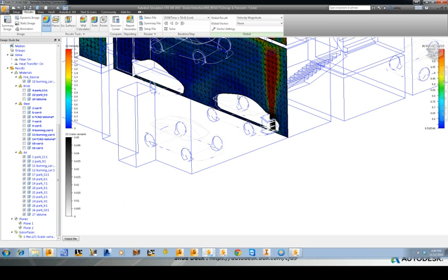Good stuff. Well, no more questions really coming in. Paul asked if I used any mesh enhancement tools. I didn't in this case. It is often really useful to use surface refinement, because it helps with the control of the boundary layer if we've got very large domains, so we can minimize the kind of blobs that we're seeing with the ISO surface by improving the boundary layer without necessarily changing the mesh too much. So if we utilize that surface refinement, it can be really useful. But the gap refinement isn't so applicable here because generally there aren't any small gaps like a valve that we need to focus our analysis around.